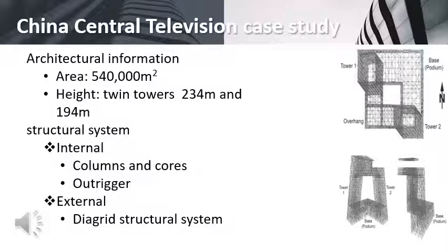For the external structure, an external continuous tube system was used by fully bracing all sides of the facades to deal with the permanent and temporary loads on the building, with the jagged structure in the building. The advantage of this combination led to less material required, more open and free internal spaces, better ability to redistribute the loads, and simple construction technique.